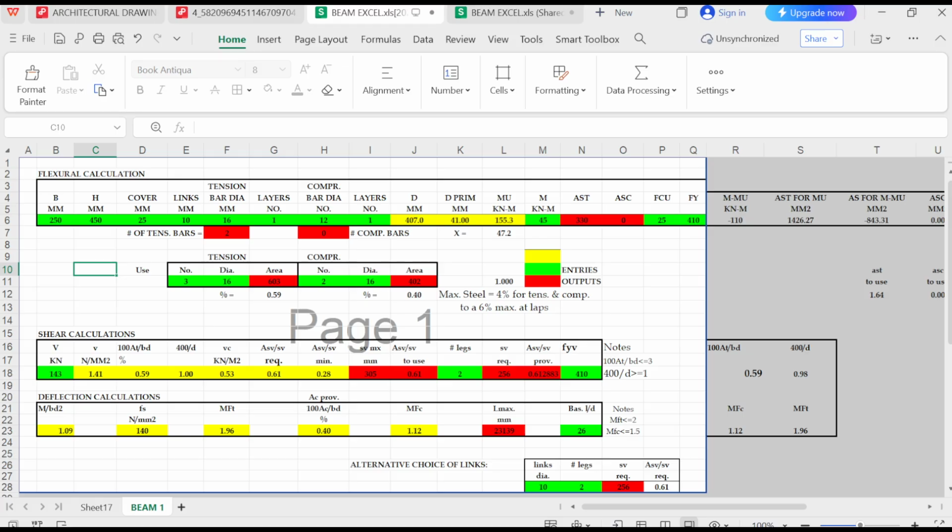Yes. So it's telling me that I need to provide a reinforcement of 330 millimeter squared. That is for the area of steel. Now for 330 area of steel, let's check for 12 mm. Let's say 3Y12. For 3Y12, for 12 mm, I'm having 339 mm squared, okay, which is okay.